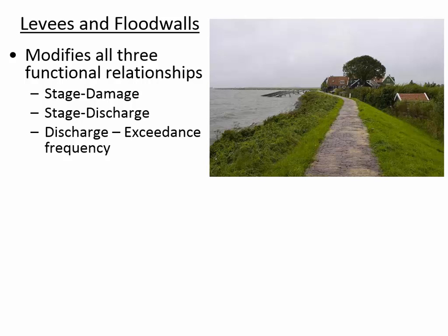Let me dim the light so you can see that a bit better. Okay, in the picture of the levee, you can notice that here's a roof, and the roof level is at about the same elevation as the river. A levee is a big earthen wall that allows water to be conveyed, and then you can develop the property that's lower than the water line. Ordinarily you wouldn't be able to do that, because usually rivers are below the population center. When you've got a levee, you can have the population center lower than the water surface elevation.